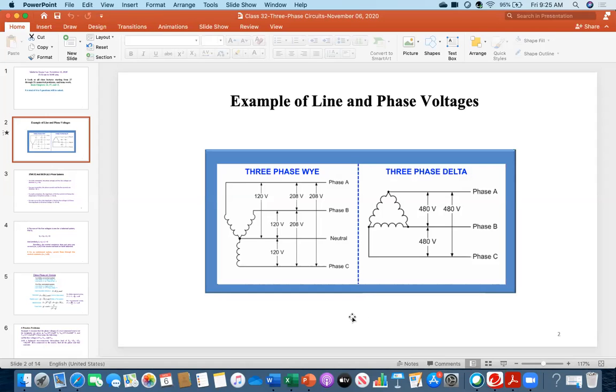If the grounding place in the soil is kind of wet, or it's a rainy day and current is flowing, so you might get shock. That is dangerous. And it depends on how much current is flowing. You might get severe shock if you are barefooted. So that's why an unbalanced system is not desired. Always it is preferred that the system should be balanced.